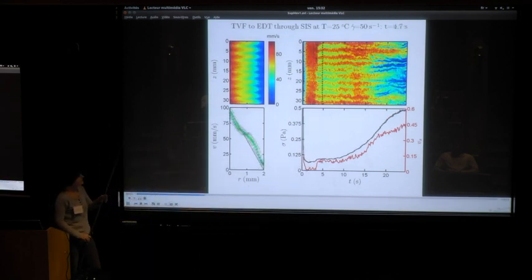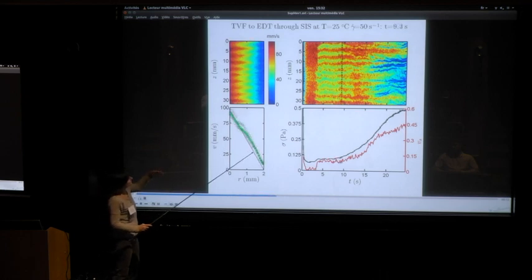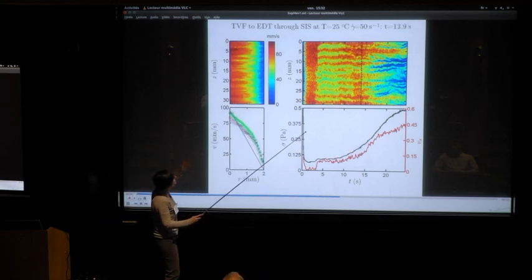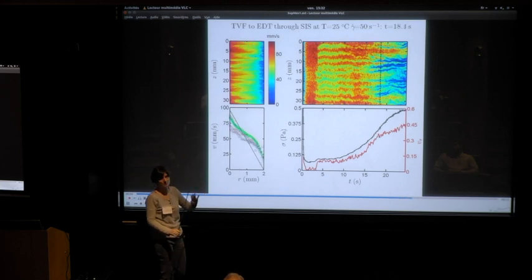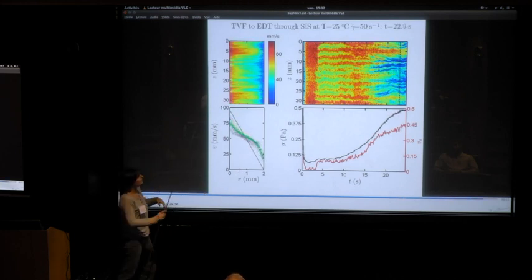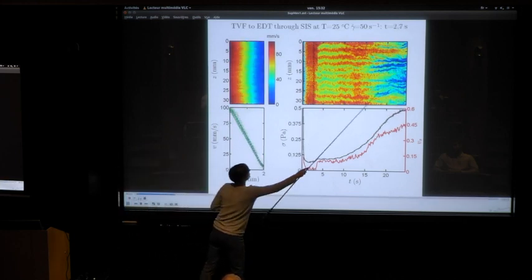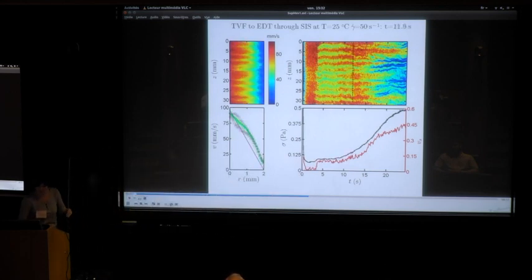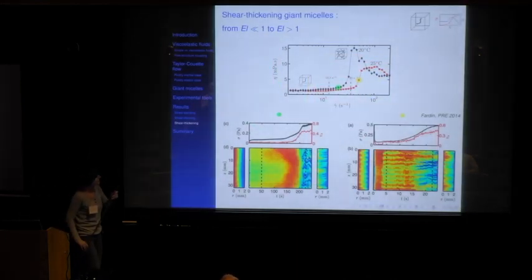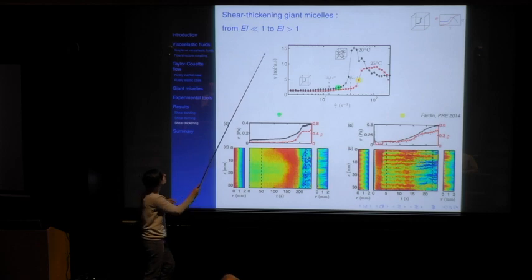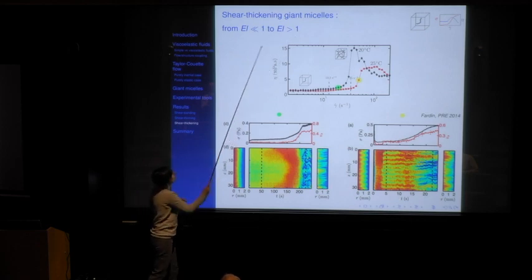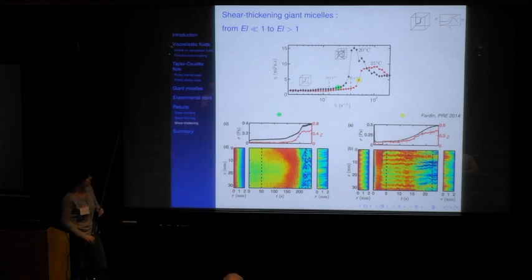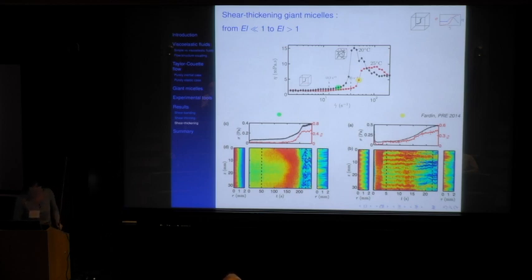The statistical properties of this disordered flow state remain completely to be characterized. For the moment, we have not at all studied the properties of this case, but by just computing the dimensionless numbers, we know that we end up with a state where the elasticity number is larger than 1, and we have competition between inertia and elasticity, but elasticity dominates.